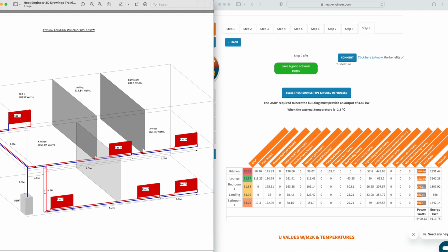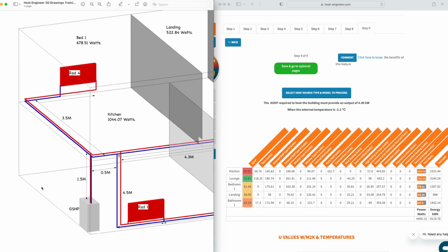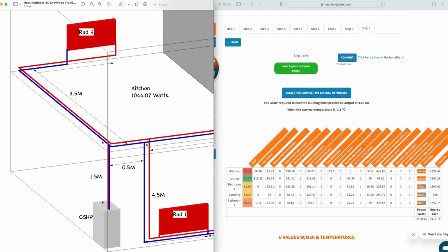But there's another thing in there, and I'll show you this. I've done some drawings on this to show you and highlight it properly, so you can stop the video whenever you want if you're just taking your time to learn all these things. You can see that I've added different measurements in, so from the primary heat source running out to T1 there, that's a section. So that's your primary section.